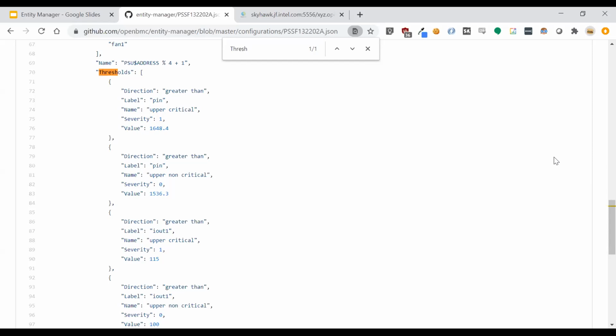You mean like getting those through PMBus or something? No, we generally can use the FRU. I know that currently FRU Device doesn't support multi-record, but we can add this support and export information from this multi-record section in the FRU, and then use it to calculate thresholds here. Yeah, that'd be cool. You could do that. I didn't know that was available in the FRU.